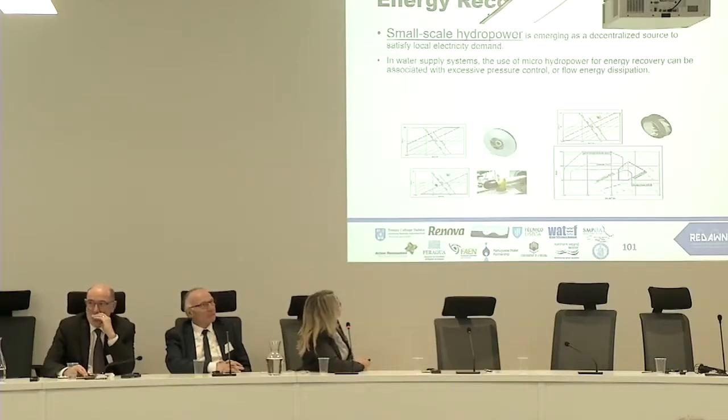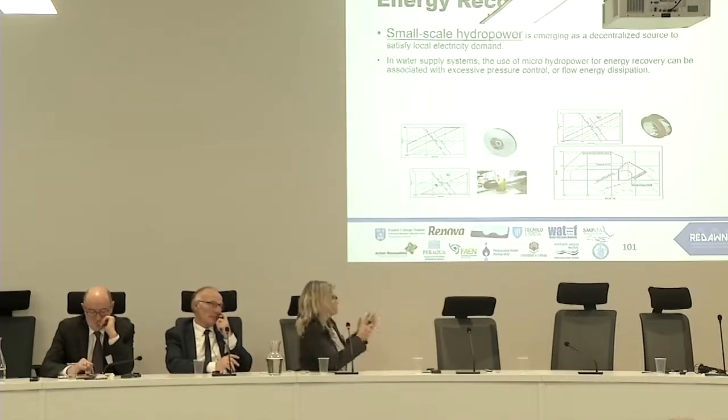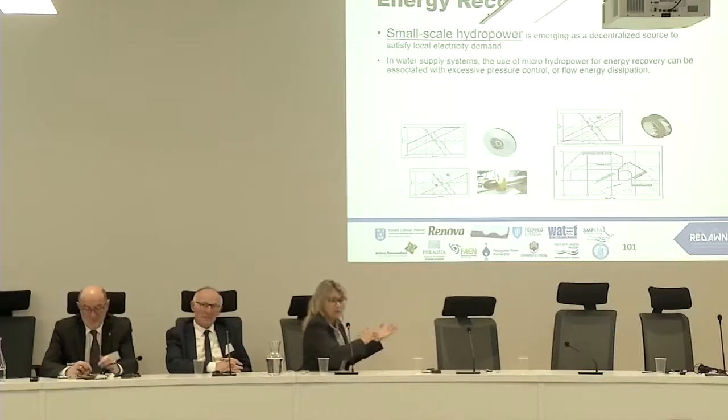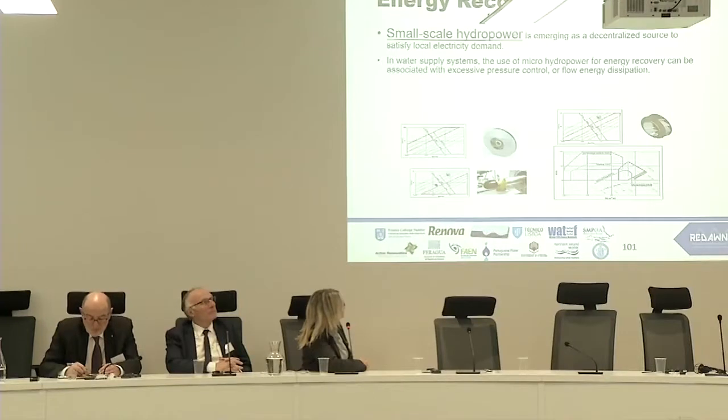In terms of energy recovery, we have a lot of types of turbines. Different turbines for high heads and small flows, medium, or high flows and small heads. Okay, we can cover these diagrams with different types of machines. If we are looking at a pump working as a turbine, we can observe here the different possible solutions, including the multi-stage, PATs, radial, mixed, etc.